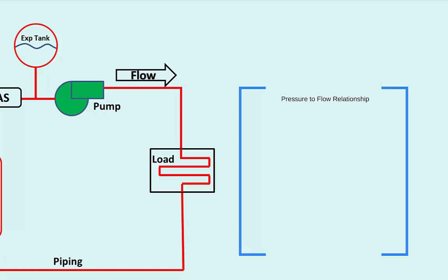There's going to be pressure drops in the water as the water flows through each length of pipe, through each fitting, valve, device, and coil. The total pressure drop from the pump discharge to the pump inlet would just be the sum of all those individual pressure drops. Now, say you actually wanted to double the flow to 200 GPM, but nothing in the system configuration is allowed to change. That is, you will keep the same size pipes, valves, fittings, etc. Increased flow will result in increased pressure drops through each of those components.